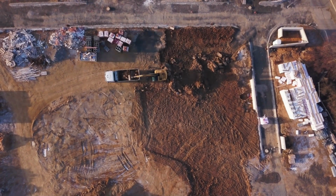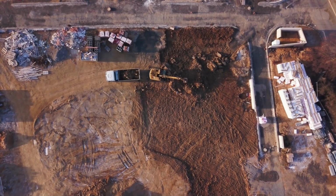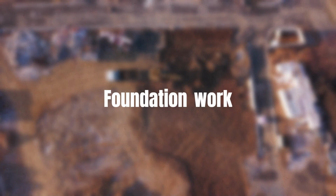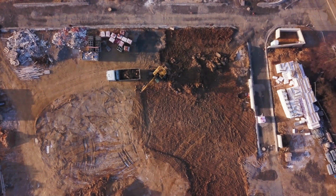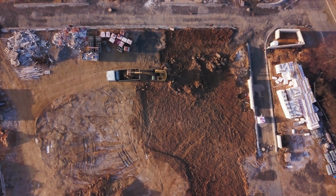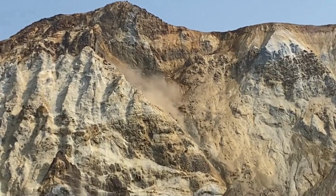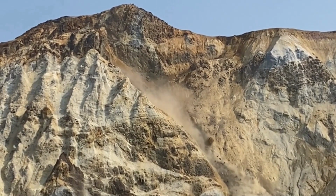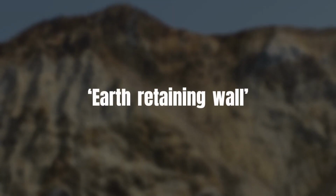Then this week, let's look at the first step of the basic construction process of the apartment, as we mentioned above: the foundation work. First, the process of compacting the ground is required. When the ground is compacted, the soil must be excavated to provide space for the foundation of the building. In this process, the soil around the site is likely to collapse. Then, what are some ways to prevent it?